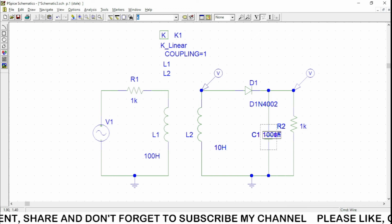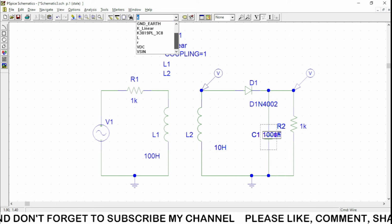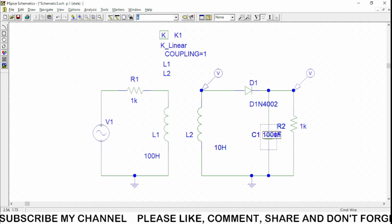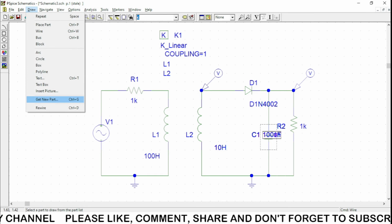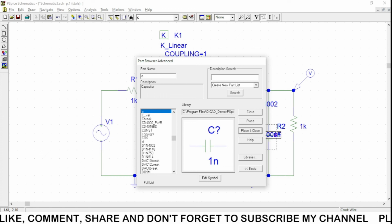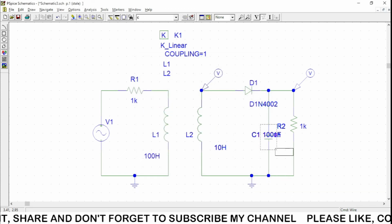This is the dictionary where the previous things that I have taken will be available. By shortcut you can take the component if we need it again. So I have taken C from that, or else I have to go to the draw menu, get new part, then press part name, type C, and take the C from there. Okay, so this is the value of the capacitor.